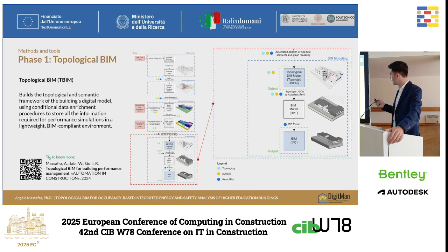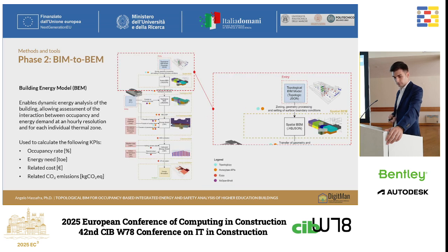And finally, once all the information is within this model, we produce 3 different models that are aligned because they are generated together and have the same information, but are in 3 different formats. The first is a topologic model, that is an abstract model representing spaces with all needed information, a Revit model that we converted using a PyRevit plugin, and finally an IFC model.